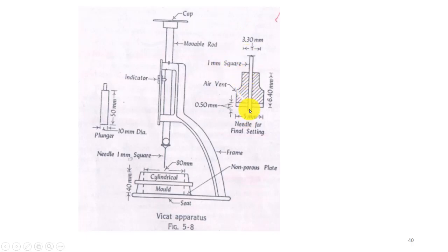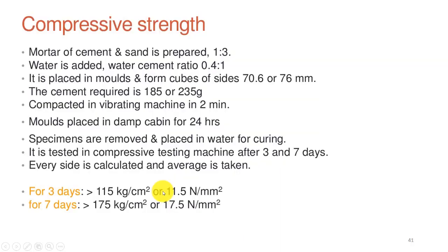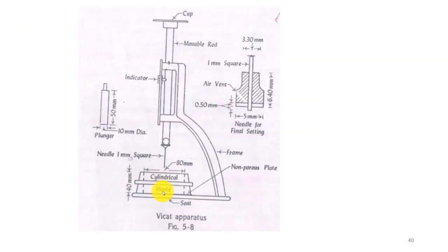You note down the penetration of the needle. When the penetration is 4 to 7 millimeters from the bottom, we can say that that time is the initial setting time.